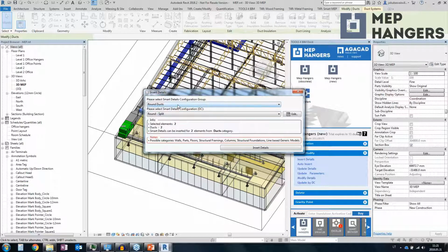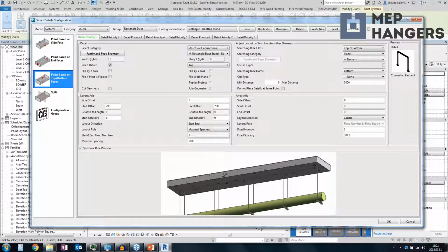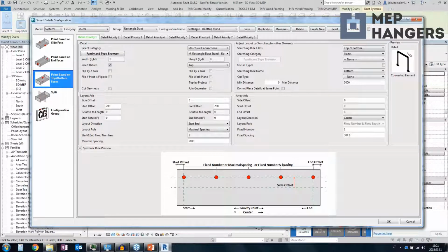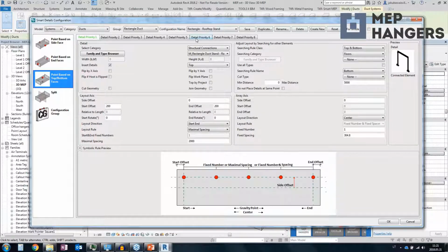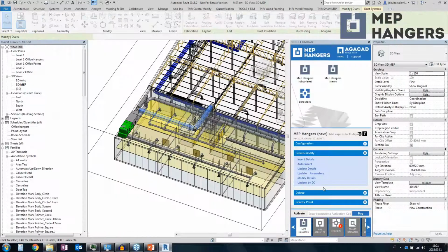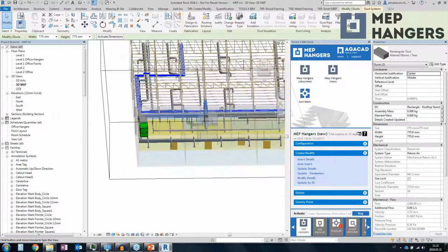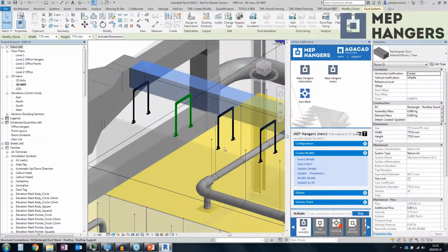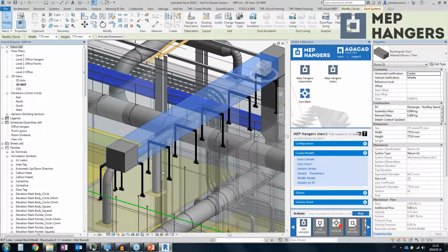in our configurations. But right now, if we speak about the rooftop objects, we can choose the family. I just downloaded the family from the network. It's a Hilti stand. It has two parameters, width and height. I added duct width and duct height parameters as well. Then I'm using that family. Then I'm inserting. It is calculating the distance to the bottom, and it is placing stands like a rooftop stand. So my elements are placed in this way.